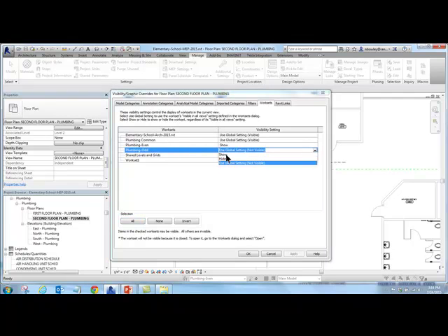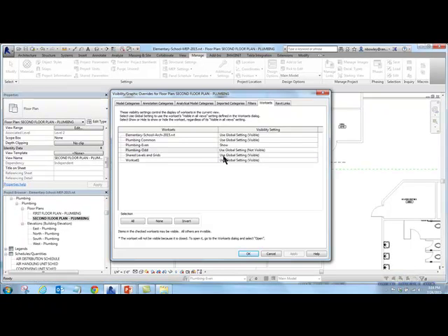So if I'm on an even floor, being second floor, fourth floor, you turn off the odd work set. Common is still on, even is still on. If you're on an odd floor, you turn off the even work set. I didn't come up with it. I thought it was a cool, creative idea.